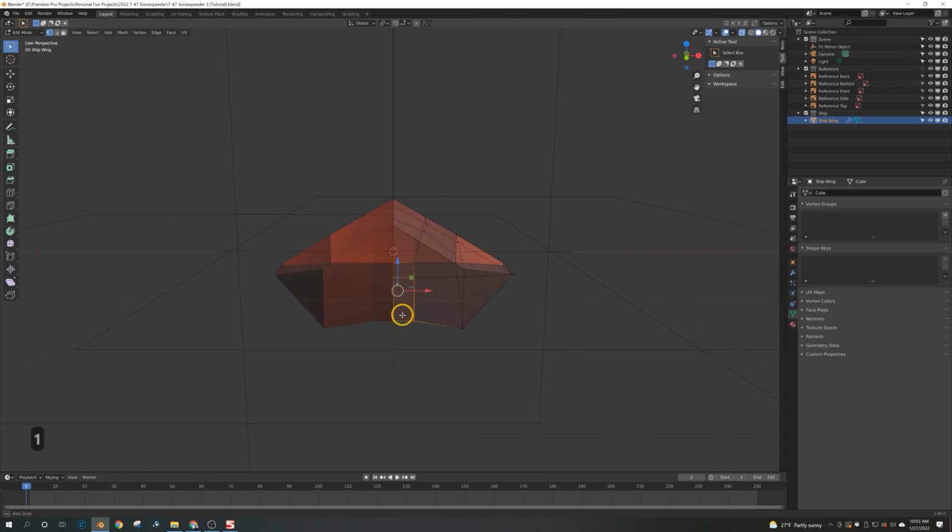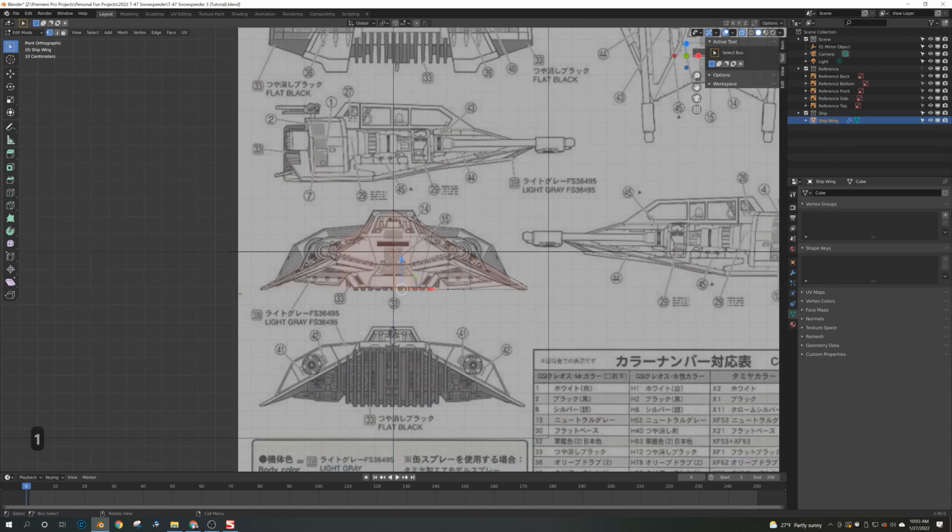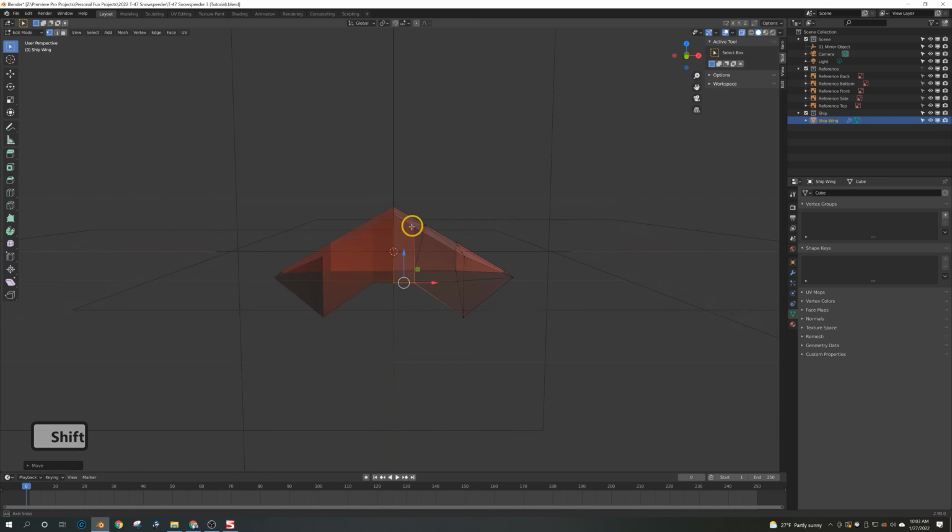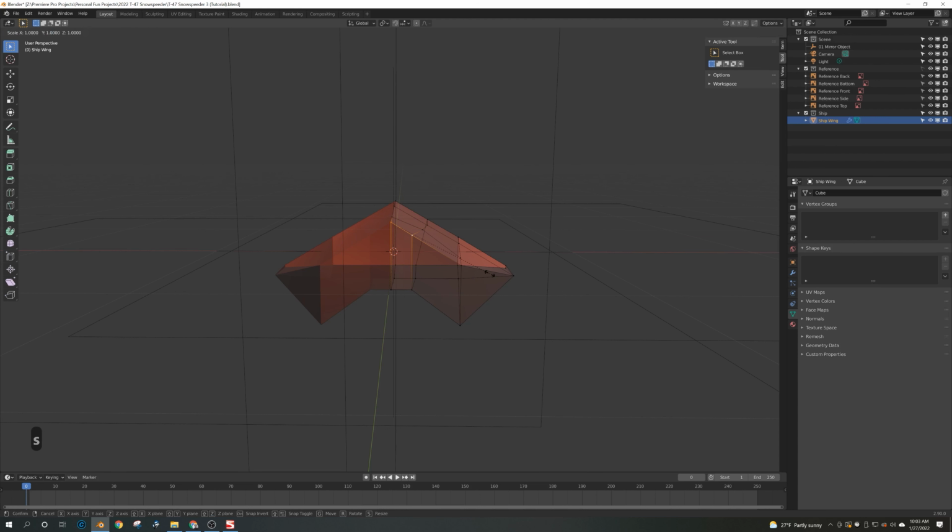And these two, I can see, are gonna need to come up to there. These two are gonna need, first of all, to come down, but they also need to be aligned flat on the Z-axis. So to do that, we just select them both, making sure nothing else is selected. Scale, or S for scale. Constrain it to the Z-axis, and then 0 on the number pad. That brings them in alignment.